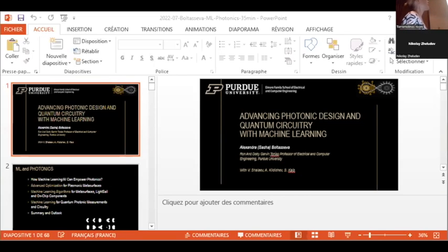So you see that these are several works from several groups. There are two papers from Igor Aharonovich's group that use emitters in hexagonal boron nitride, hBN, and try to combine them with aluminum nitride waveguides, or use them in a membrane setting. The main challenge here is not only to realize a source of single photons on demand, but to integrate it efficiently on a chip, because you really want to extract it efficiently and couple it into the on-chip waveguides in order to enable future circuitry.